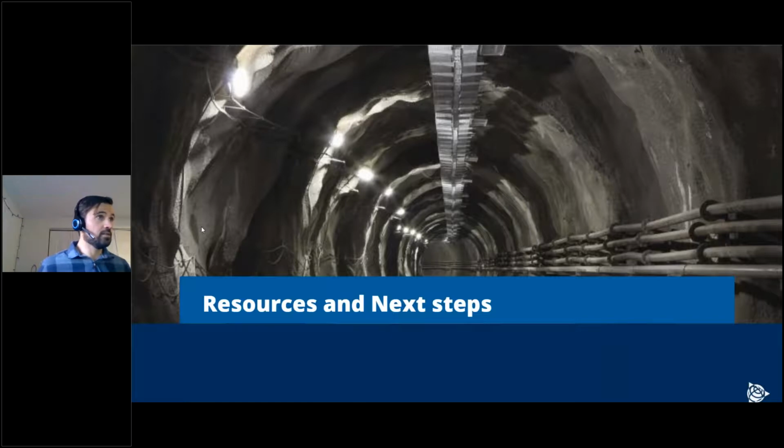So Rocky, hey Rocky, thanks for the question. Can you manually set where the sections are cut? So you can change the interval. I think this answers your question. If not, just let me know. You can change the interval in Trimble Access or TBC on kind of how often you want that to be. So it's 1 meter, half a meter, or wherever. You can also, while you're in the field, define what station you want to measure. So if it's a really specific one, down to the centimeter, millimeter, you can define that while you're in the field.